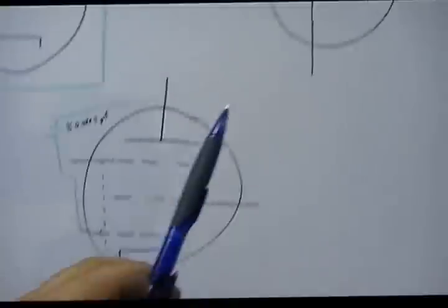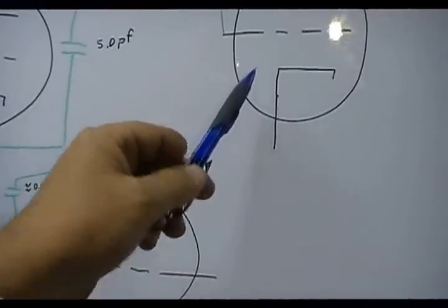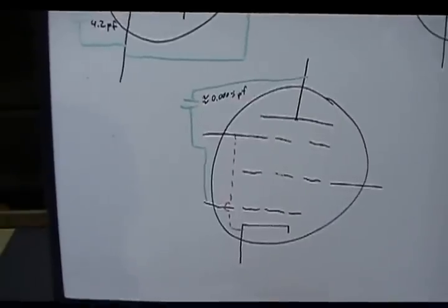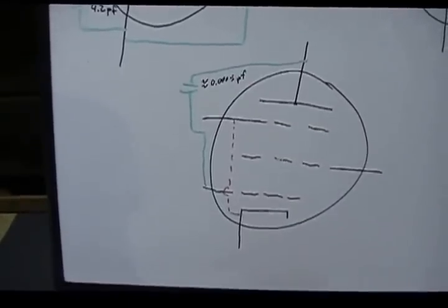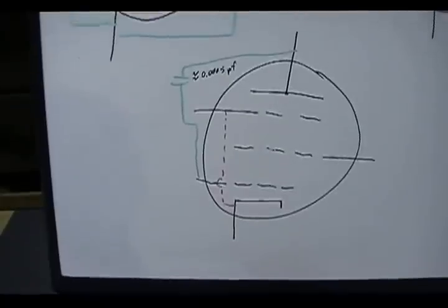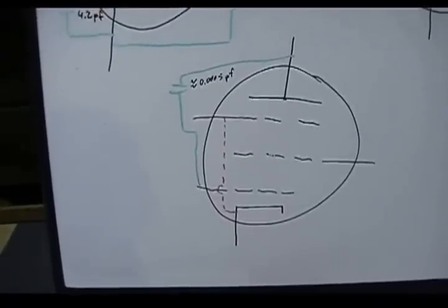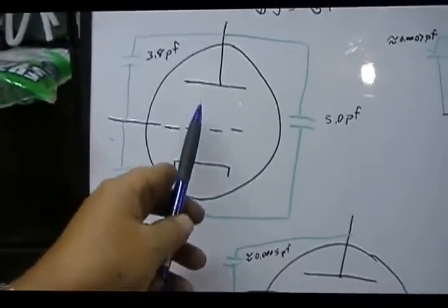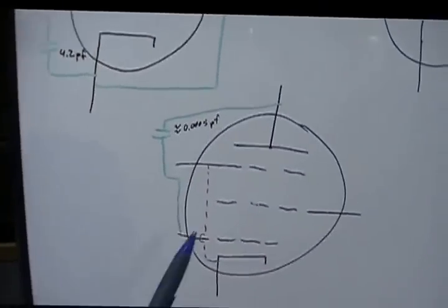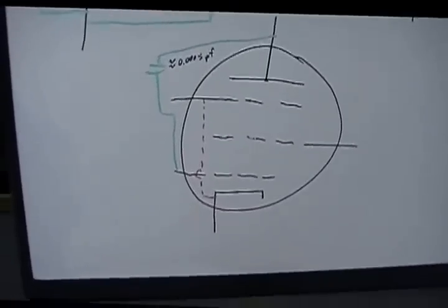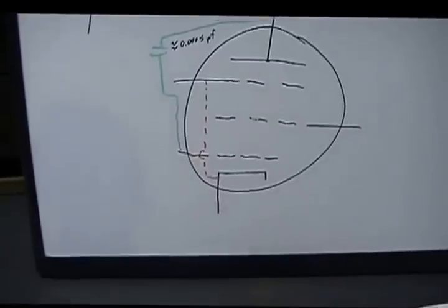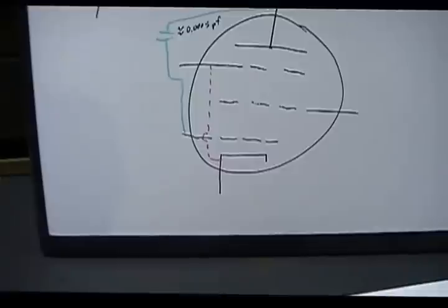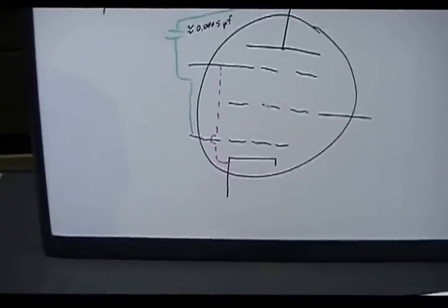Now the only problem with both these tubes, this one not as much as this one can be, is harmonics. They can be pretty bad with harmonics. They're a lot higher percentage-wise than harmonics. These average 5% or less. These 10, 12%, which can be disturbing to the ear. So you have to deal with that when you design an amplifier and work with that problem, and we'll get into that.